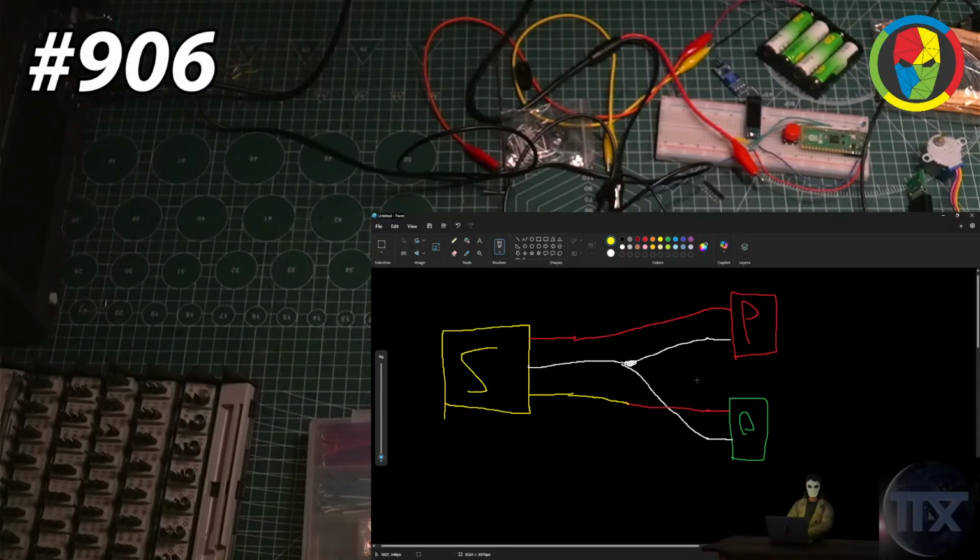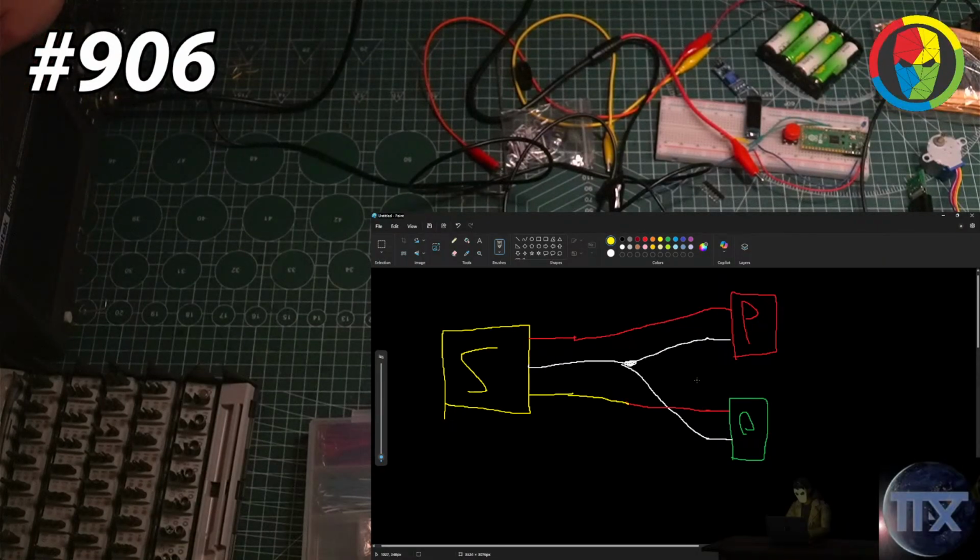I don't know if I'm going to use the wave generator much. I don't know what it does exactly. It's just used to generate a wave. Yeah, you could generate a clock. Is it an adjustable generator? I don't see a knob for it, so I do not know. It usually just generates a signal so that you can adjust your probe on your oscilloscope. That's the only thing I use that signal generator for. But there are standalone signal generators that a lot of hardware hackers use to send a proper clock signal or to overclock, to increase the clock signal.